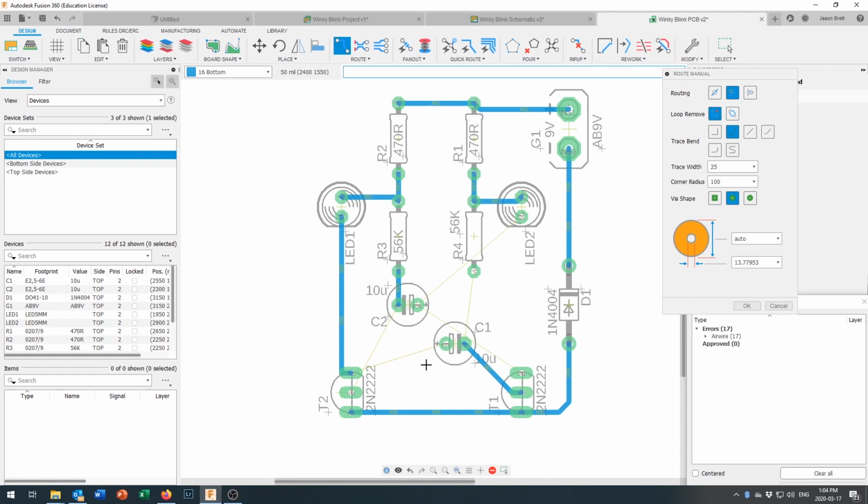It's beautiful right there. And now we've got some that are getting a bit trickier because they cross right here. Now, this one needs to go from here over to here. We can't come down this way and cross across here because we'd end up crossing this air wire and our nets would run into each other and they'd join together and there would be much sadness in our circuit board. So we're going to come to right here. We're going to run underneath that resistor, come down here, and zigzag across our board like so.